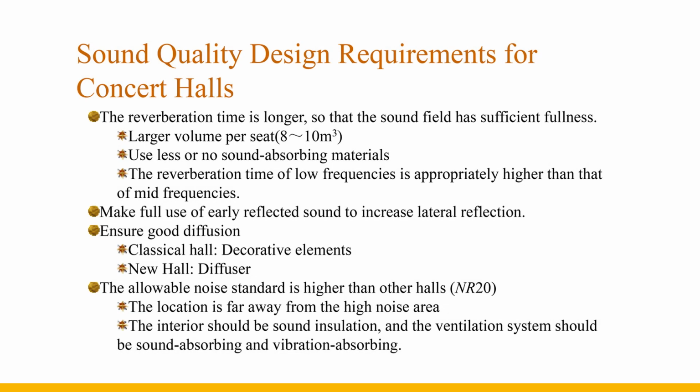The performance seats and the auditorium of the concert hall are in the same place. There is no orchestra pit, there is no separated stage place, and most rely on natural sound. The sound quality requirements are the highest in all kinds of halls. The sound quality design should meet the following requirements. The first, with a long reverberation time, the sound field has sufficient fullness.